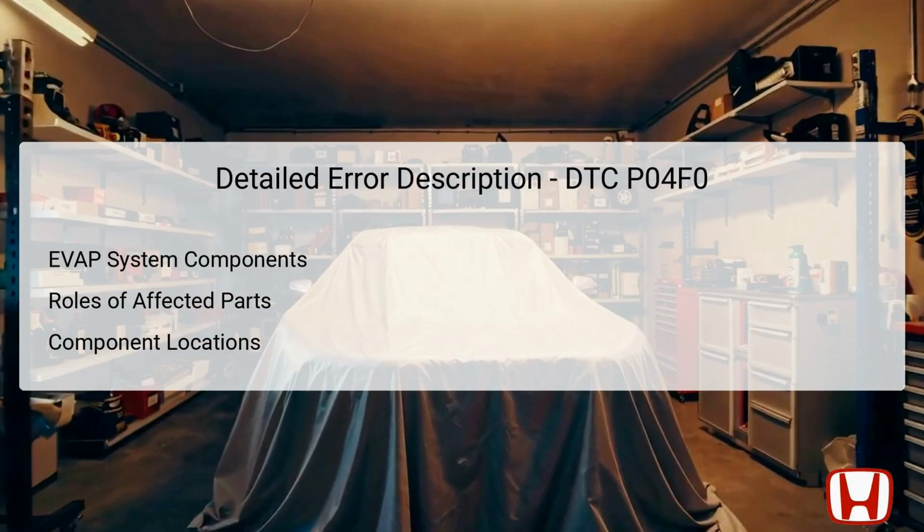The DTC P04F0 indicates a fault in the EVAP system related to the flow of purge gas. Key components affected include the Evaporative Emission Control System, EVAP, canister purge valve, located typically near the fuel tank. The EVAP canister, which is responsible for holding fuel vapors, and the purge tube, B and D, which facilitate the flow of fuel vapors to the engine. Additionally, the non-return valve, integrated with the EVAP canister purge valve, prevents backflow, ensuring that vapors are directed toward the combustion chamber efficiently. Each of these components plays a critical role.